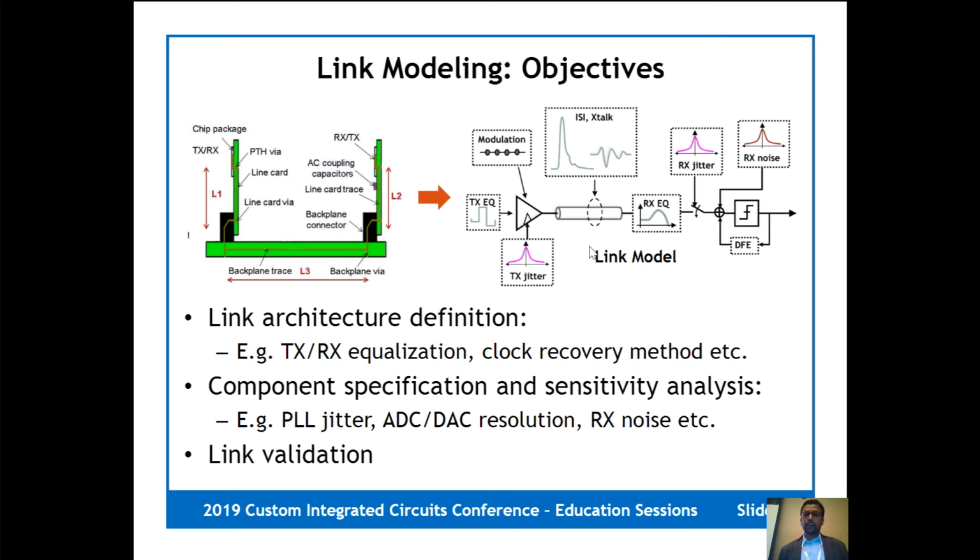So typical things that people study are the equalization architectures, how to divvy it up between the transmitter and the receiver, and between different forms of equalization, continuous time versus discrete time, linear versus DFE, and so forth. And similar analysis on the clocking side as well, to figure out how to break your jitter budget between different clocking elements.